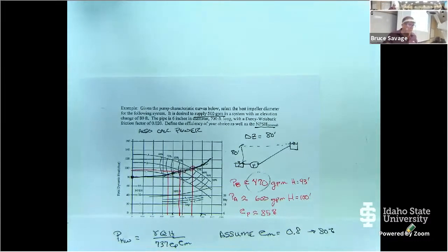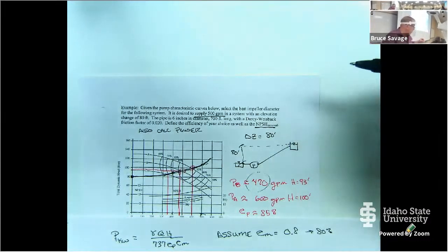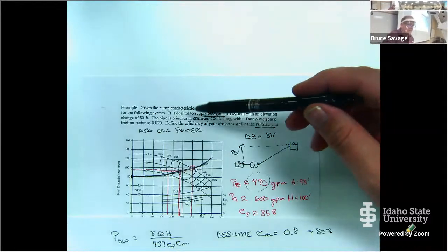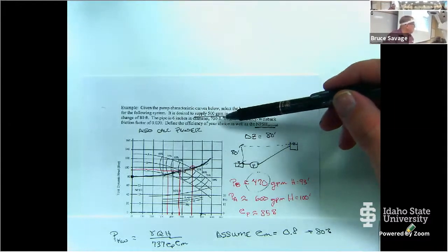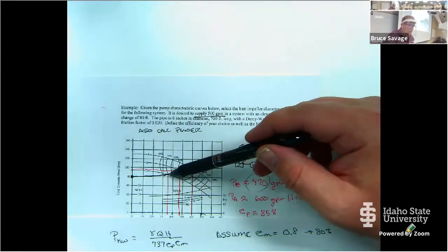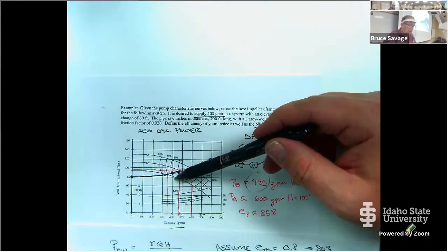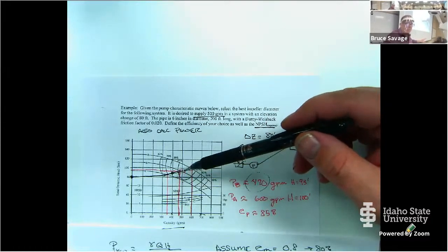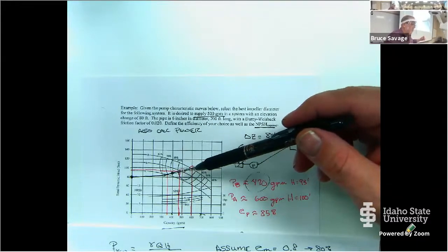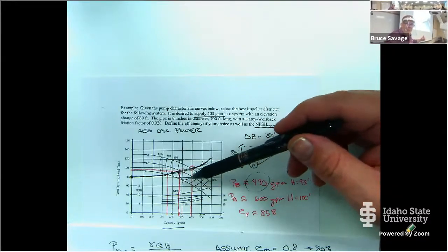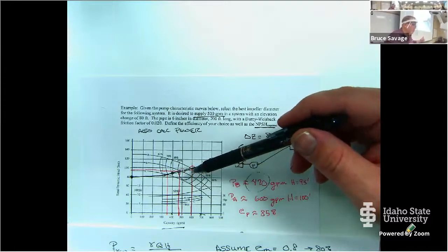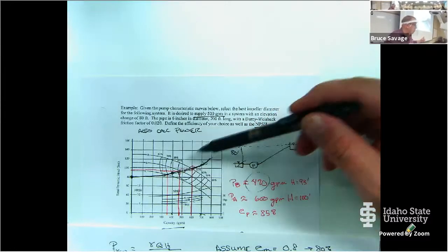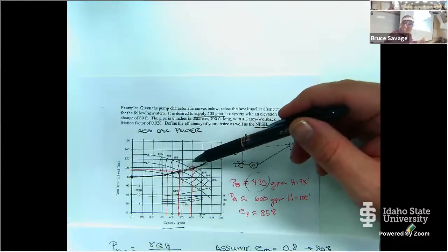It's a really good question, but let's come back to our problem statement. One of our design parameters is that we need to supply 500 gallons per minute. So C, which is down here where it intersects, only gives us 350. We know we're way below the parameter, so that impeller does not meet our design parameter. So that one's gone. Pump B, if we're being really strict about our design parameter, if I've not drawn the curves correctly, does not meet it either.